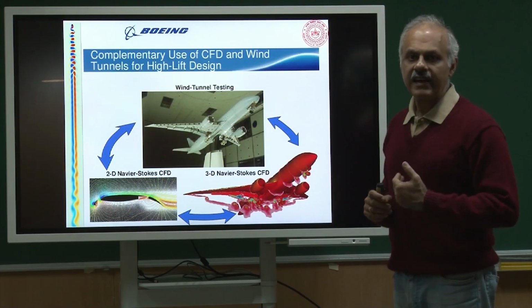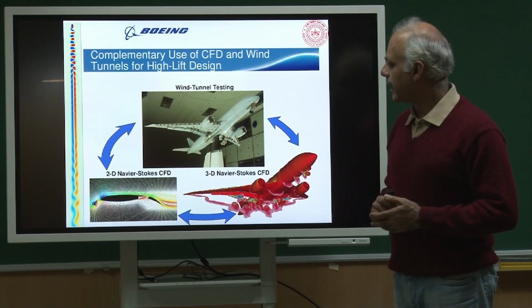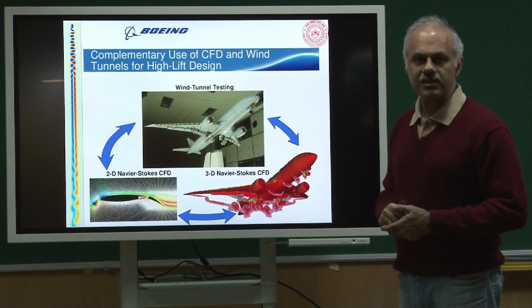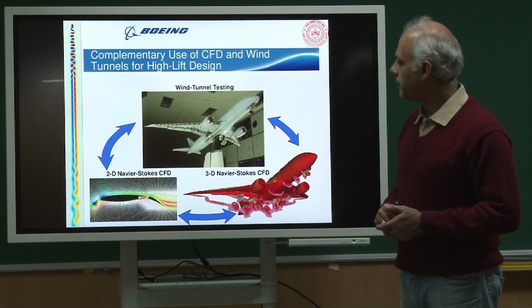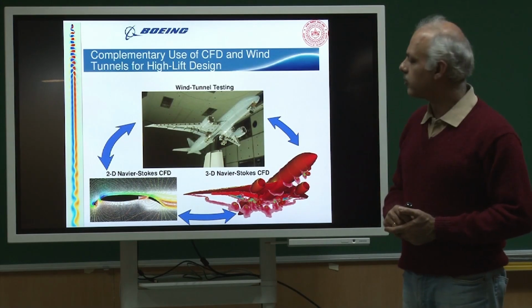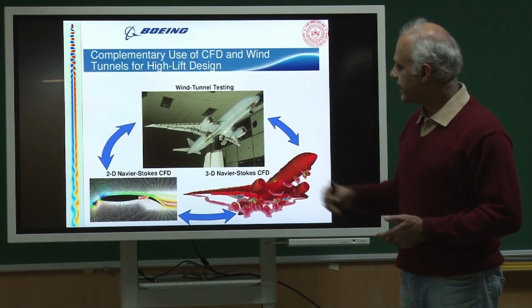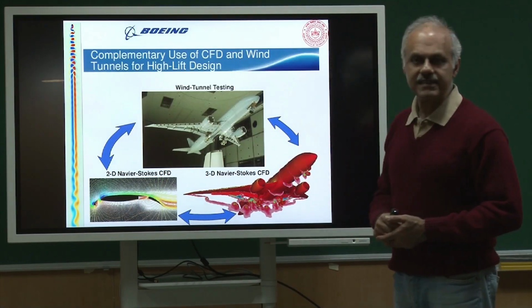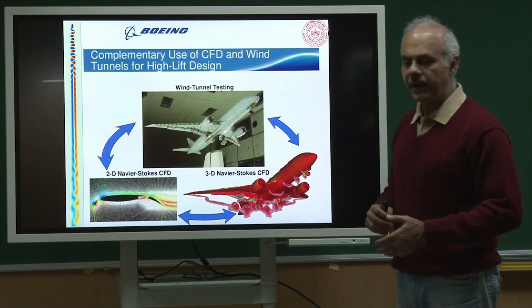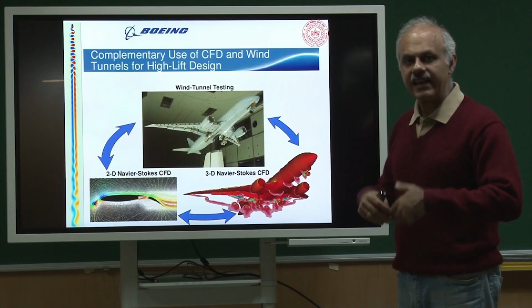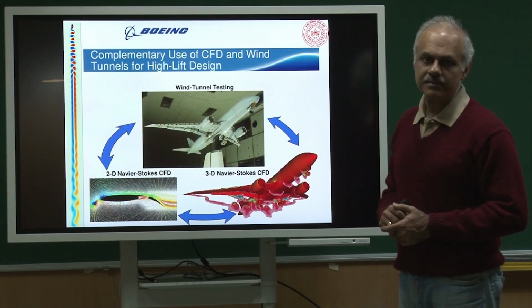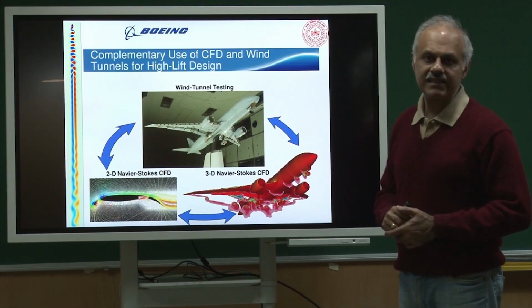Now by using dynamic similarity, I can estimate what should be my wind tunnel speed or the speed of the air for the given size of the aircraft that I have scaled down to. And then I can put this model on a balance, measure the forces and moments and calculate the coefficients, and then again scale up the coefficients to calculate the forces for my prototype. So that is typical wind tunnel testing.